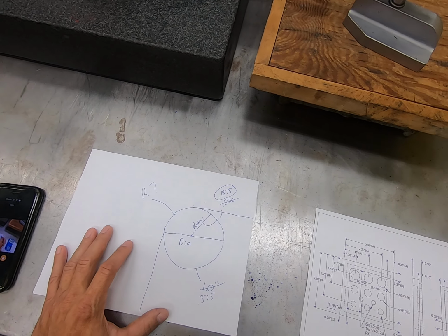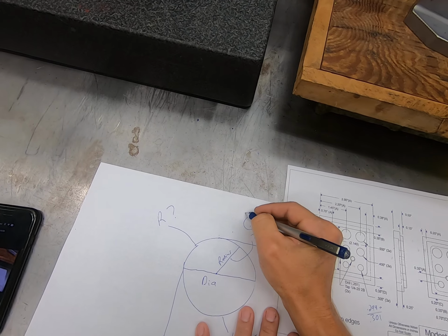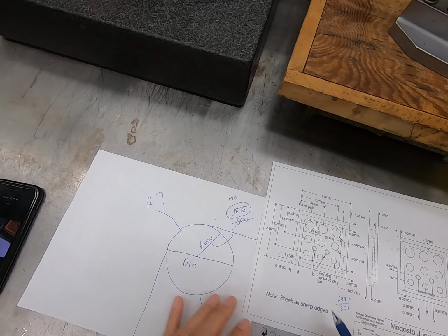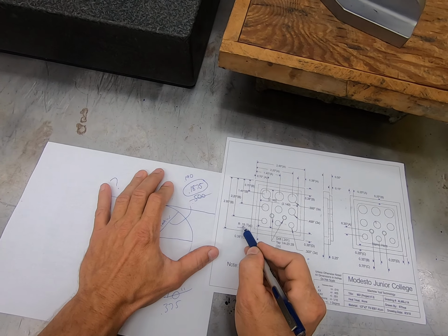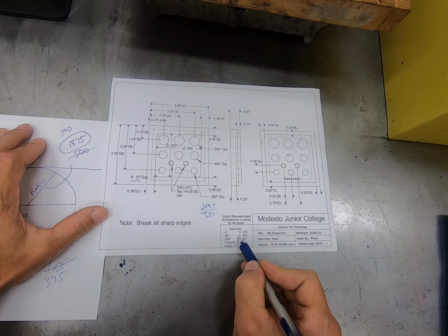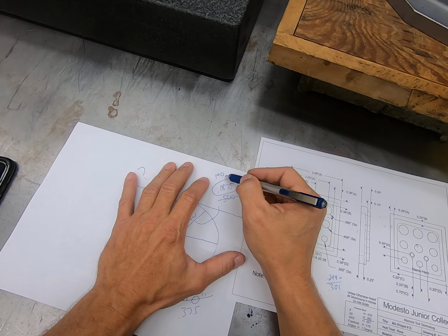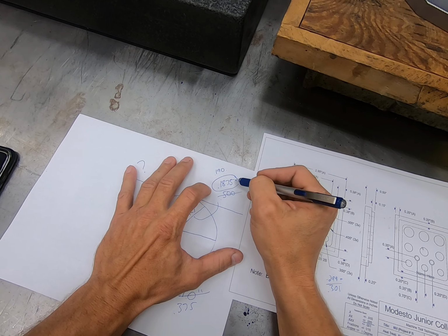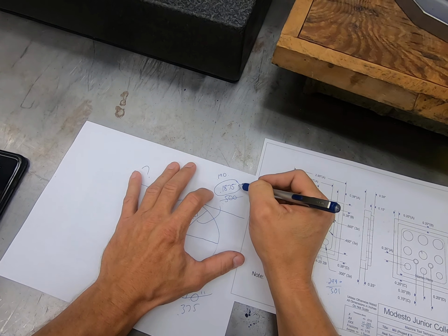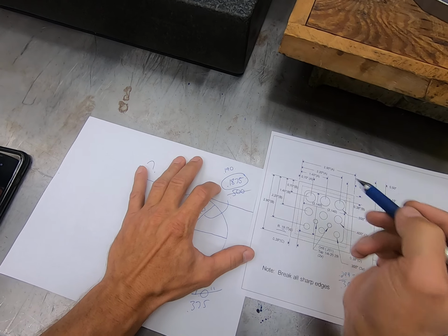If we go back to our blueprint, it's called out at 190 thousandths, so 0.190. Since it's only called out to 2 decimal places, we go down to our drawing, and in 2 decimal places we get plus or minus 5 thousandths. If we're looking for 190 and we achieve 187.5, we are within specification. We will still meet that tolerance and it will still be considered good.